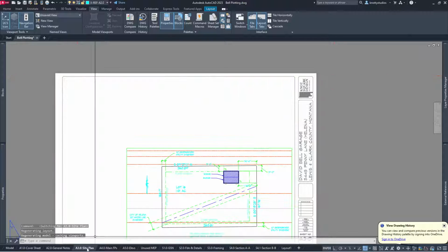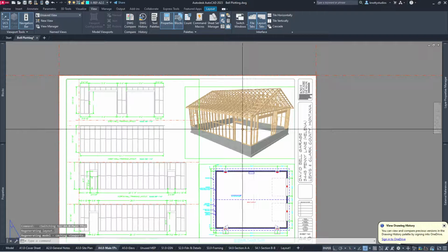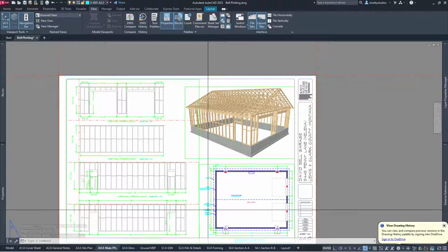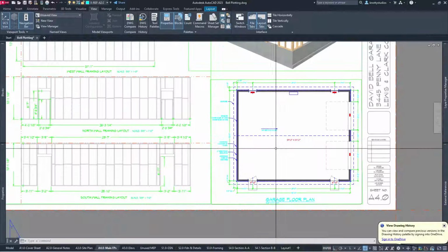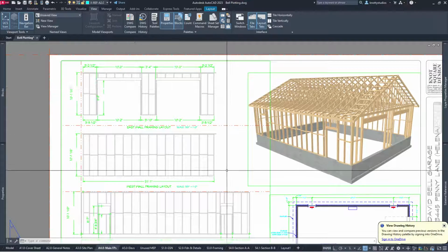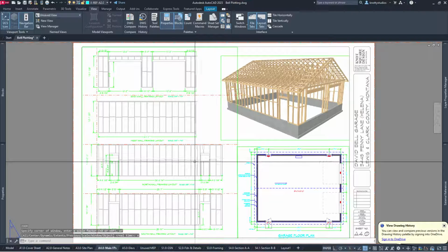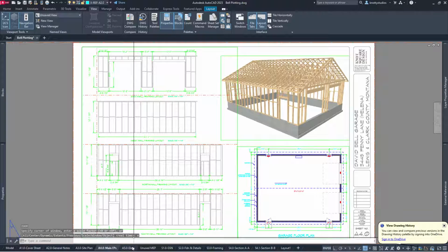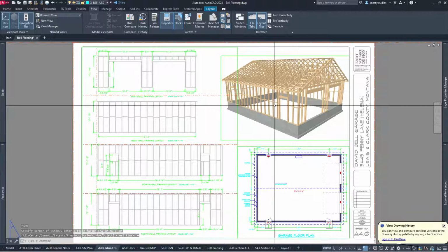So then we have a site plan sheet, which is going to disappear because it's now part of general notes. We have the main floor plans, which includes the 3D view of the framing, the floor plan itself, fully dimensioned with some notes as to what is what layer and everything that you see here. And then each wall, it shows how to frame it. So it's a pretty complete plan. This is way beyond any garage plan. But this is what I was talking about. This is the experiment. This information and this 3D view came out of Chief. So this is where I'm combining the two softwares.